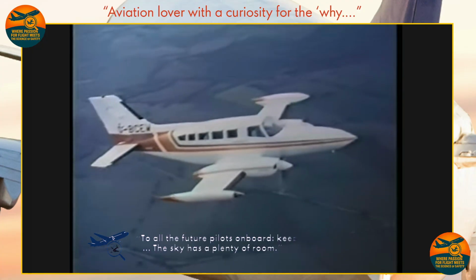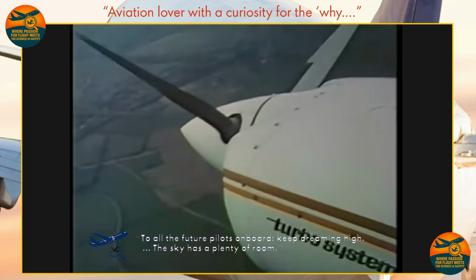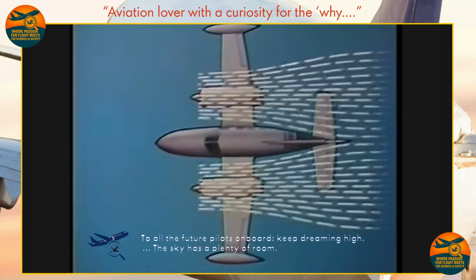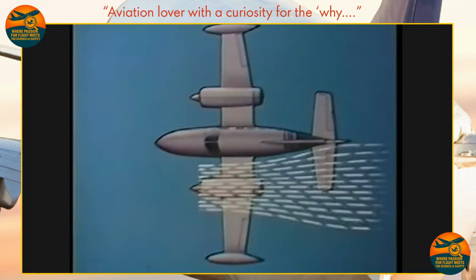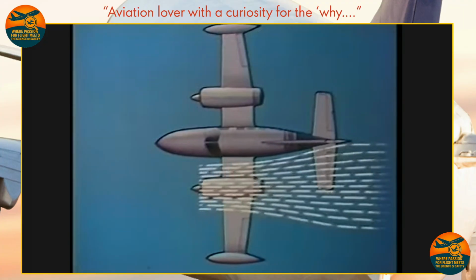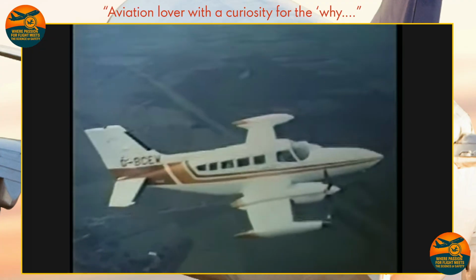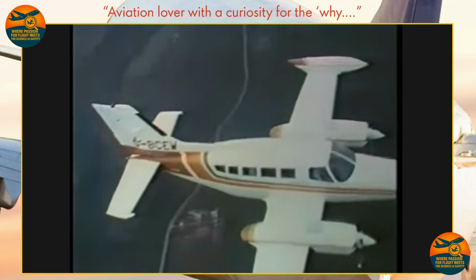However, there's always the possibility that an engine may fail. When this happens, total thrust and slipstream are lost on the affected side. Unless we prevent it, the aeroplane will yaw towards the dead engine. And the wing, having lost some of its lift, and now slowing down in the yaw, will drop.